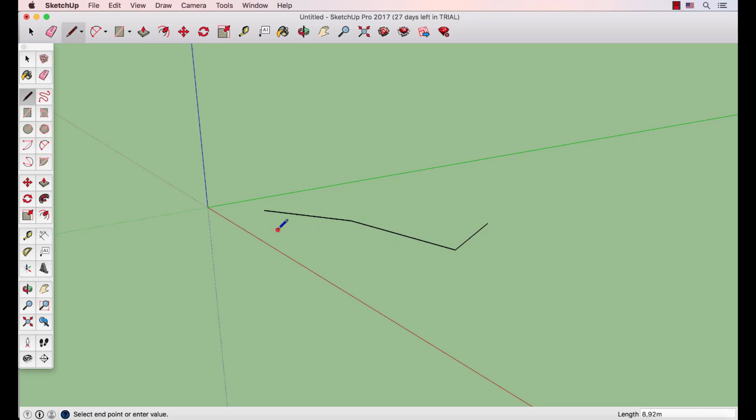With the second way, we can form a line by holding down the left click and pulling it in the desired direction. The line command stops when we release the left click. This method makes it harder to draw many continuous lines. So mainly for this reason, we prefer the first method. When we want to finish drawing lines, we just press the Escape button on our keyboard.